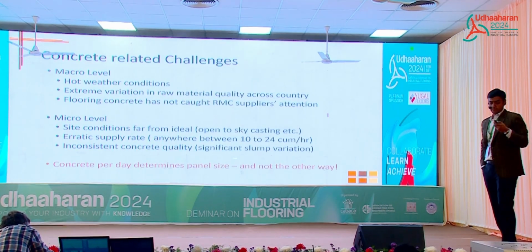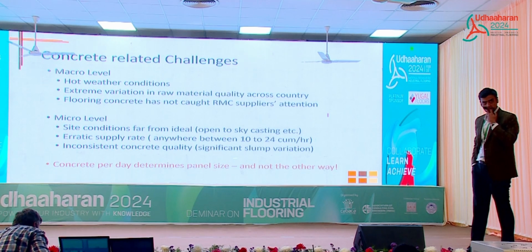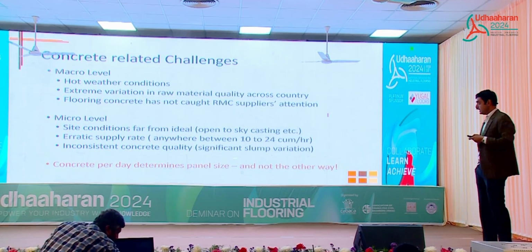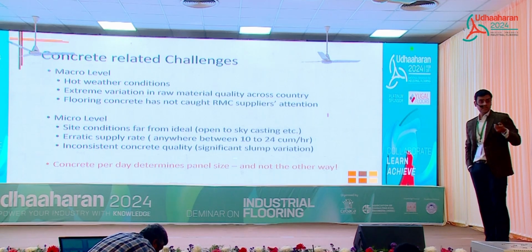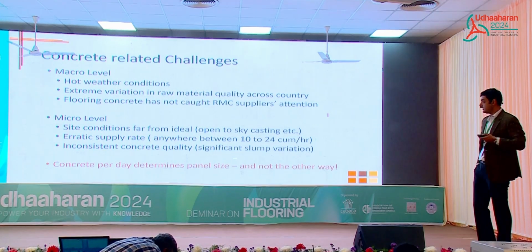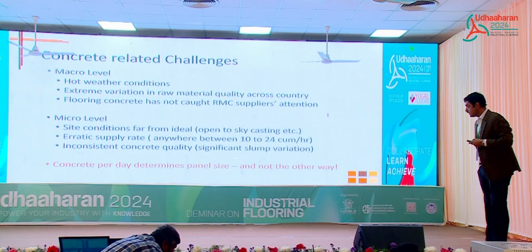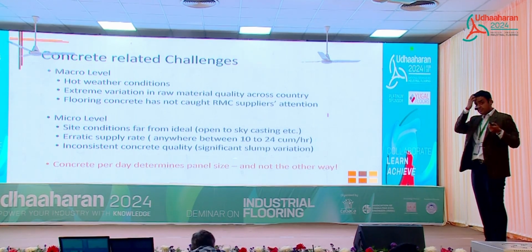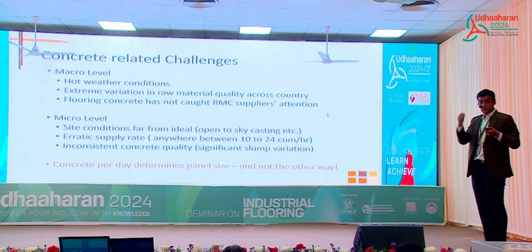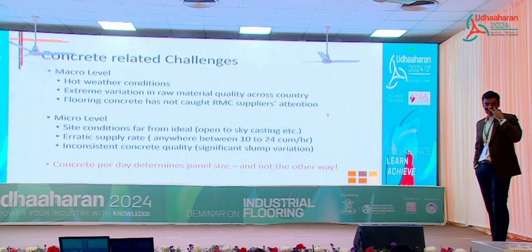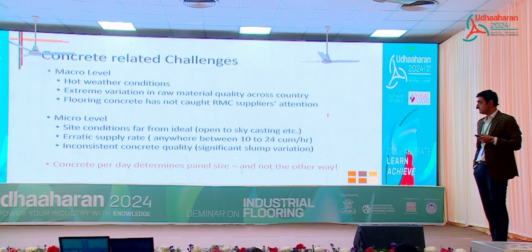Concrete, I'll talk about practical stuff, not the theory, because I can't get into concrete mix design. That would take half a day. At a macro level, what we are dealing with in our country is hot weather conditions, obviously. There is extreme variation in raw material quality across the country. As I said, we have worked in more than 15 states. We see extreme variation in sand, cement, even admixtures.